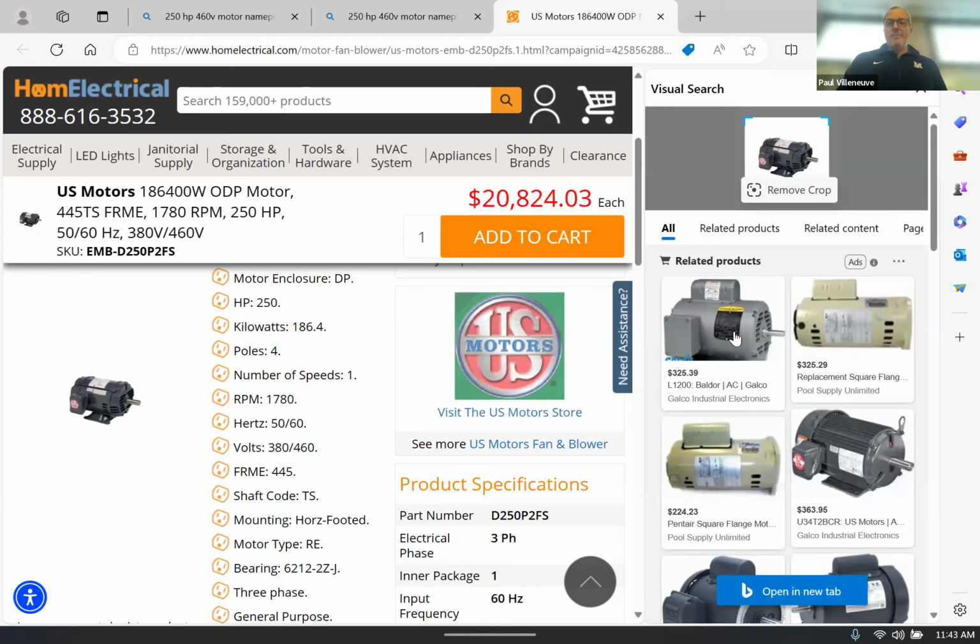Well, I guess I can't see it, but you can see on the ones over here that there are slits that are openings into the motor. So airflow can go in. And what that means is this motor can have smaller copper wires. Doesn't need as much copper. So it's going to run cooler because it has that. You can look at these.